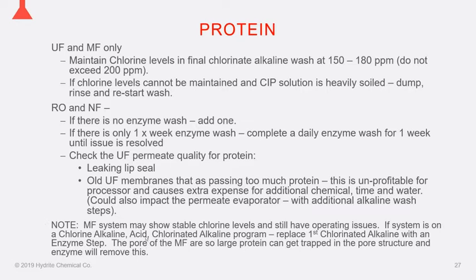ROs and NFs don't have the luxury of the oxidizer protein removal. In most cases, we're pretty much not going to want to touch them with anything that's oxidizing, but there probably should be an enzyme wash if there's any protein product involved in general. If there's not, we can go ahead and add one as a remedial step, or maybe even for a longer term period. And if there's only like a weekly enzyme wash, we can increase that to daily.